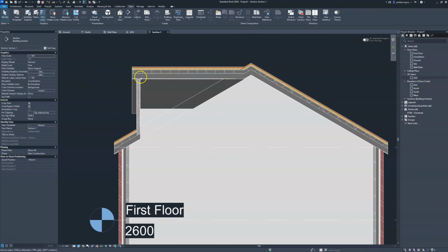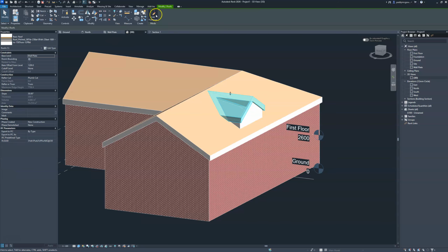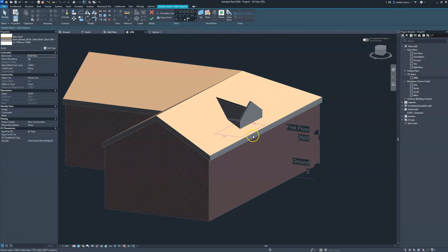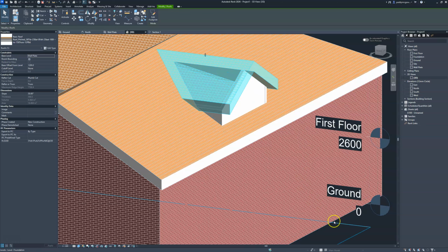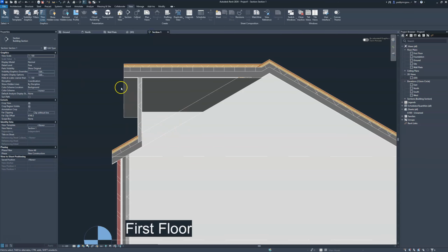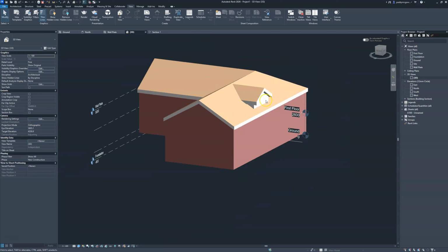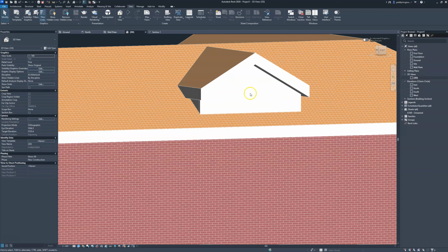We've got a little bit of an overhang, which you can increase, by the way. If you come into the sketch, go to Edit Boundary, and you can highlight on that and increase the overhang to anything you want, let's go a little bit further, just to give the look or the finish that you're looking for. Go back to our section view, then we can see a nice bigger overhang there. Okay, and then of course once you find a window that is the right size, you can start to add it on there.